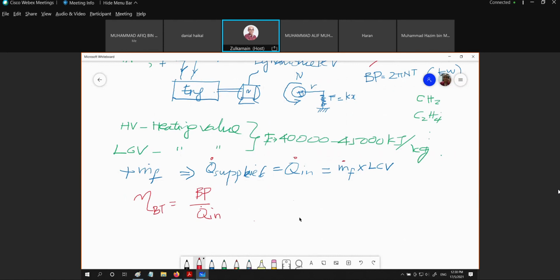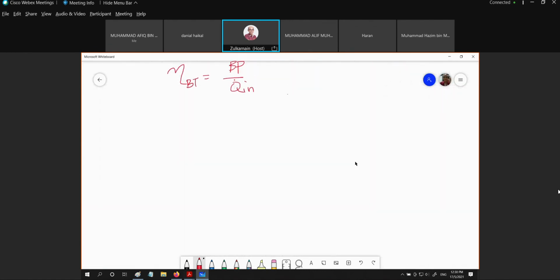Now we are going to look at what we can do in terms of the combustion analysis, whereby we try to get the pressure inside the engine, inside the cylinder. So let us look at one side of the cylinder, only one cylinder. You could have here a cylinder, let's say for our petrol engine. There is one device called the pressure transducer, which basically measures the pressure inside the cylinder when the piston moves. We try to tap the pressure variation when the piston is moving.